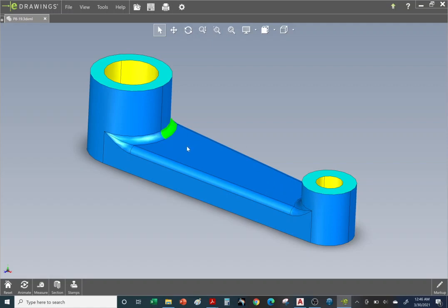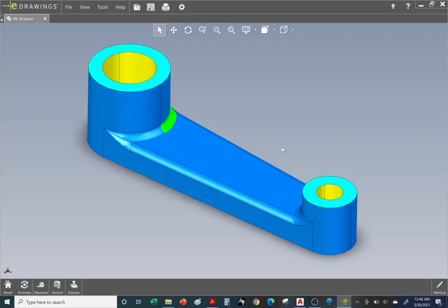But this piece needs to mate up to other parts. So this is something that you commonly see on a car, for example. It can be something in the suspension, or a good example is a water pump. If you look at the old vehicles, not so familiar with the newer ones, but if you see the water pump in an old Chevy or old Ford, it'll have a rough texture to it because it's cheaper to cast it into a mold. Take it out. Once it's solid, it'll have the rough surface. And then you can come in and machine off the surface.